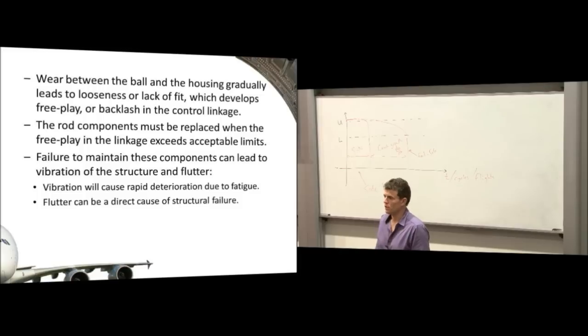Flutter is a forced oscillation where the airflow will actually push the control surface one way or another and it will get bigger and bigger and bigger. Much like if you keep pushing a kid on a swing in the same direction, the kid will eventually get so high it falls off, or it'll do a full circle. If you keep pushing something in the same direction as it's moving, the oscillation will get bigger and bigger and eventually break your control surface clean off the aircraft.